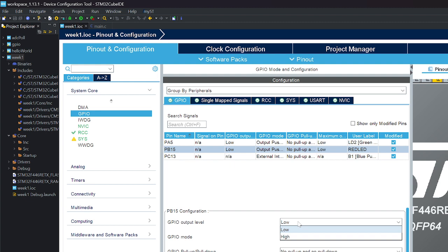The other thing that can sometimes be used here is do you want it open drain or push pull? So push pull has the transistor to the VCC, and if you want that not there, then you could have it open drain. A typical use for something like that might be when you're trying to connect something up that's at a different voltage level, and as long as your current requirements are met, you could use open drain and an external pull-up resistor, for instance, to talk to a different voltage level. So you can do things. In general, you want the output to be push-pull.